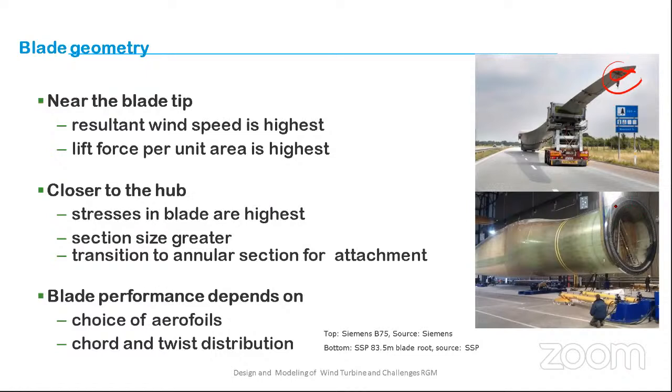Just look here. Stresses will be more on the blades here, because now you can see your hand, extend your entire hand. Have you ever read in the newspaper that bowlers always get pain in their shoulder? Why? Because they are continuously bowling, giving more cyclic stress. The blades also, because the blades are mounted on the hub, experience very high stress.